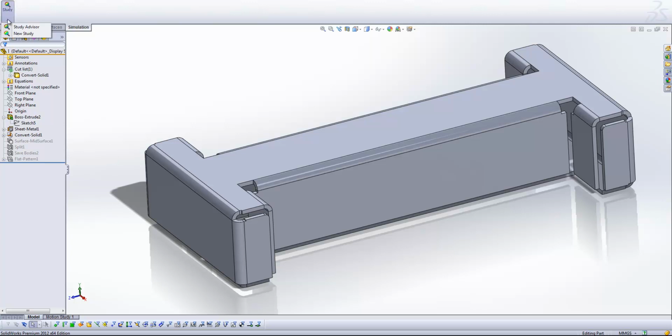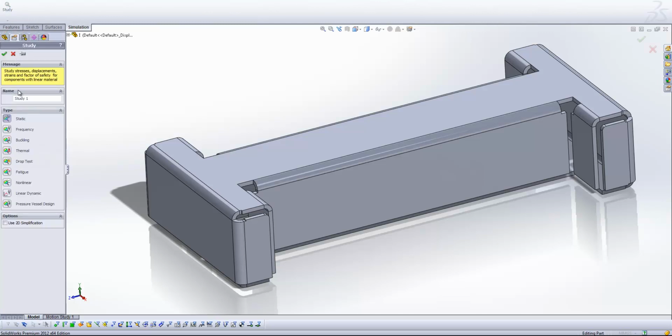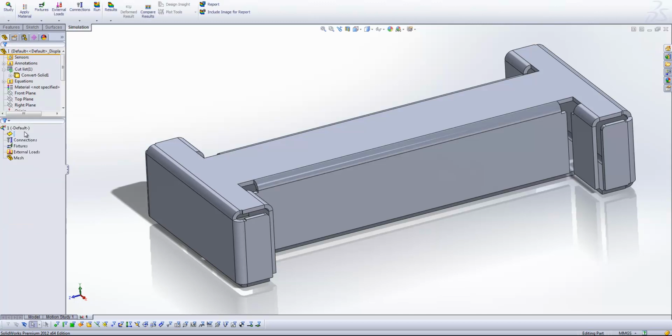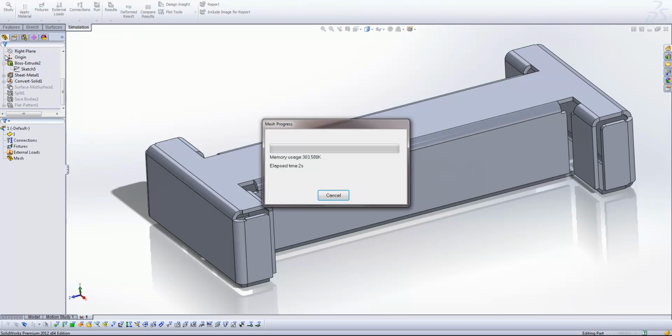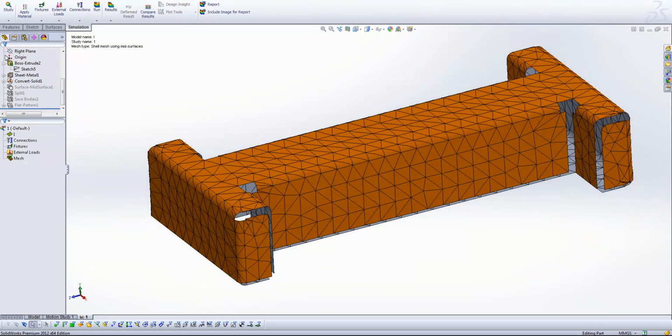component. Hopefully, first of all, you'll be aware that SolidWorks by default assumes that because we've generated our geometry using the sheet metal tools, that we want to generate our mesh using the surface mesh tool. So if I just right click on the mesh here and have a look at that, you'll see that what we get is a two-dimensional mesh, and what SolidWorks is going to do is extrapolate the information that it generates from this two-dimensional mesh into 3D results.